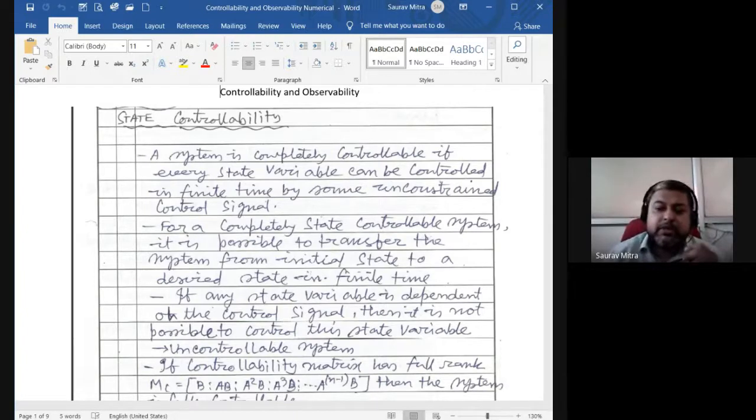So this is a numerical we had done. Given was a differential equation, from there the transfer function, from there the companion form. From the companion form, you are finding the ABCD matrix. From the ABCD matrix, again you could verify C(sI - A)^-1 B + D. You could verify whether it is generating the same transfer function or not. If it is generating the same transfer function, it means it is describing the same differential equation. So this was another type of numerical.